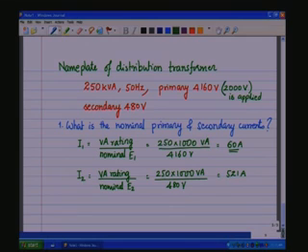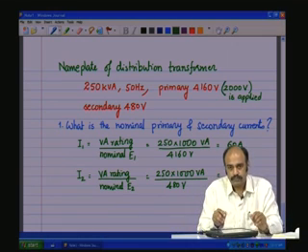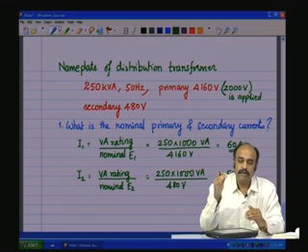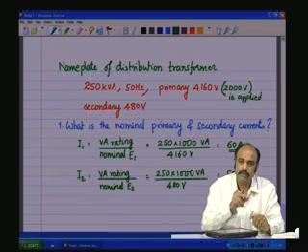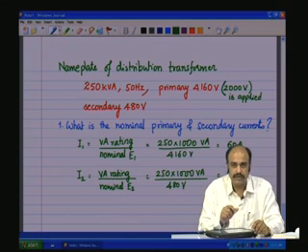That is the question. Now, if we take the transformer, we are applying a voltage which is lesser than the primary, which means the volt-second is smaller for the same frequency, which means the operating point in the BH curve is going to be smaller. So, a smaller BH loop is going to be traversed, and therefore, the transformer is going to run cooler.